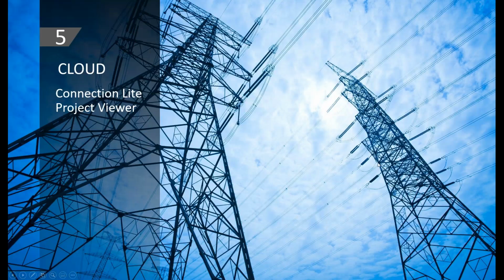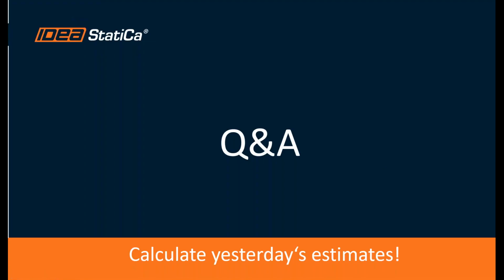Yes, of course. Thank you, Martin. So you can now import a curve from DXF, which can be a line, a polyline, or a spline, and you can import it into IDEA Statica Detail and apply a line load on it. Of course, the line load can be in all the directions that were previously available for the regular line loads. Now it will be applied onto this curve, which is, as I said, a line, a polyline, or a spline defined in your CAD application.